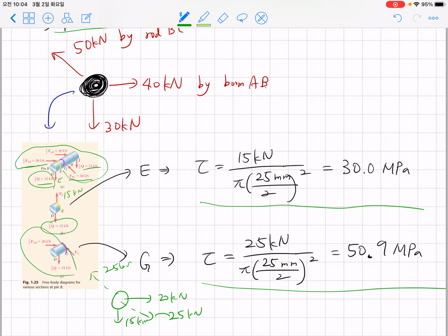In addition to this complexity, in later lectures, we'll consider the so-called stress concentration effect, because the governing equation of stress distribution and the governing equation of electrostatic potential are quite similar. When you have a lightning rod at the top of your building, you're going to have an electric field concentration at the tip of this lightning rod, and that's why lightning strikes the tip of the lightning rod on the building. So it's the same here.